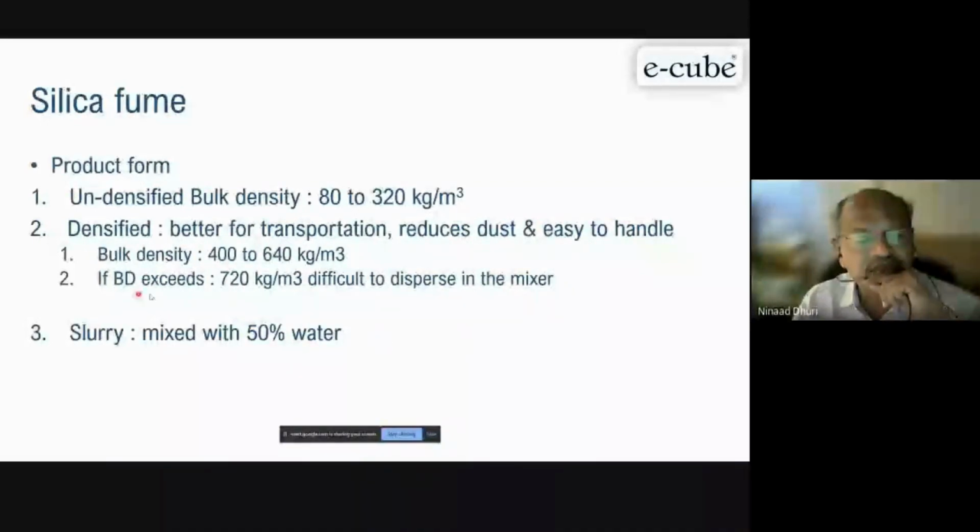Because when you are designing, you may be using powder form. And when you are batching actual production, you go in the slurry form. So extra water available from the slurry has to be reduced from the main total water, the designed water, maybe free water or total water we have designed. Suppose it is 200 liters and 50 liters is coming from this slurry itself, then we'll have to use only 150 liters of water. That also is a precaution one has to take.